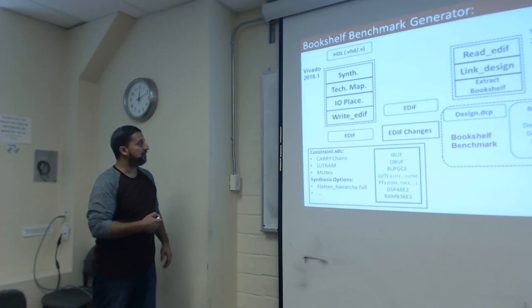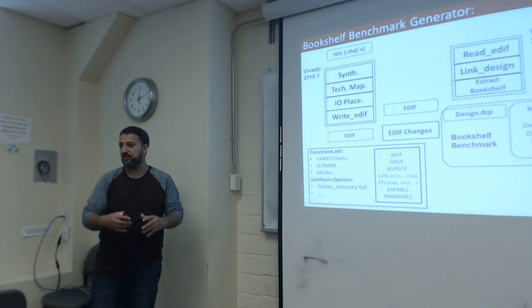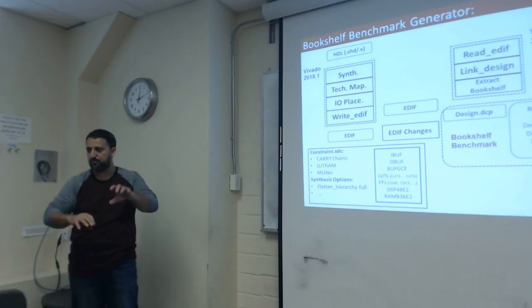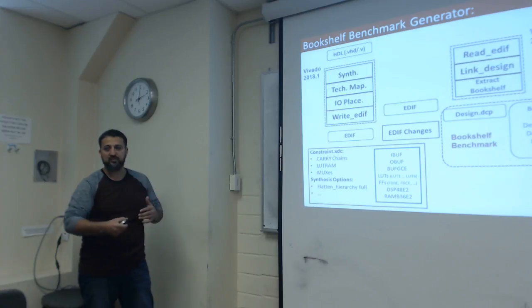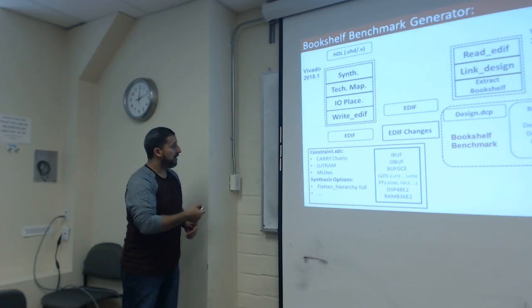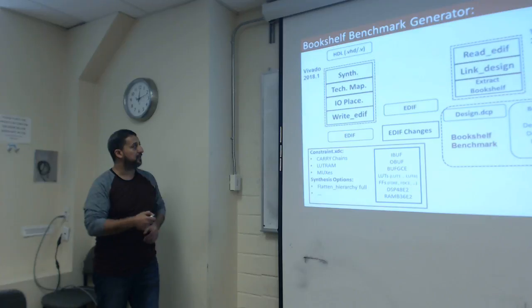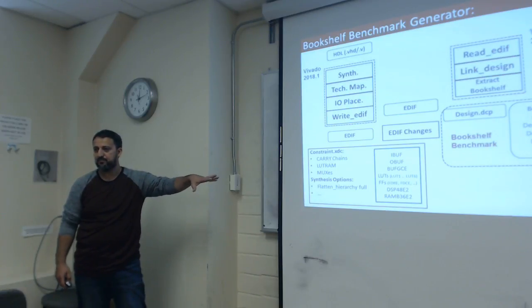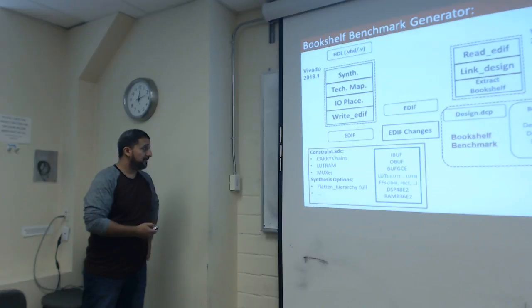We found that the new Vivado has more options and constraints that we can apply as block constraints. So we write some wrappers for the original design to have one block, with separate blocks, and apply those constraints and options in the synthesizer for the top-level block. We found some useful parameters here that we can use to generate only bookshelf netlists that have the same components as in the competition. That's what we have right now.